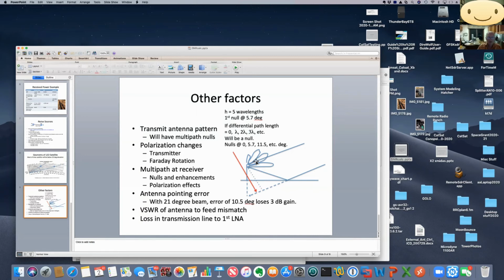And it knows that one of two things happened. Either the ground never received it, which means that the satellite has to retransmit it, or perhaps the acknowledgement half of the exchange got lost, but still it retransmits the packet. It doesn't lose anything. So that's a very common ham radio protocol that AX.25 TNCs quite often use.